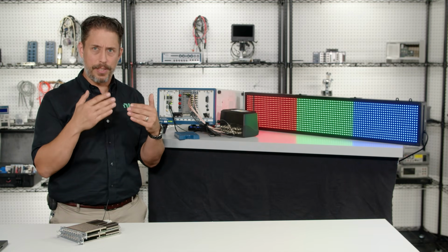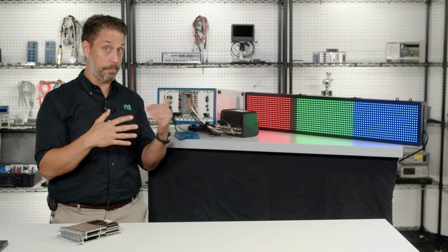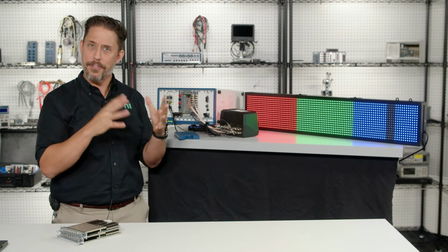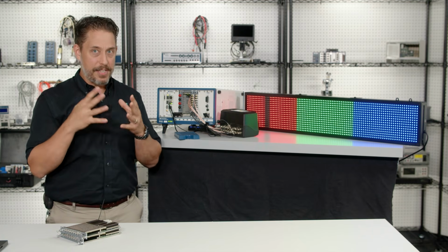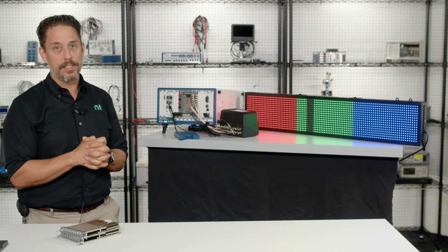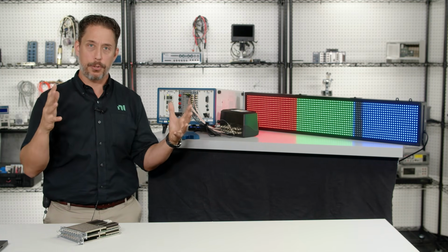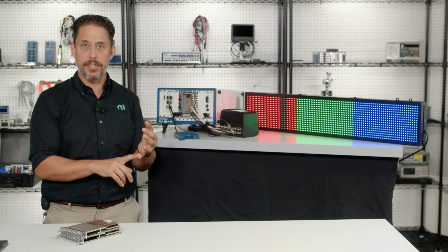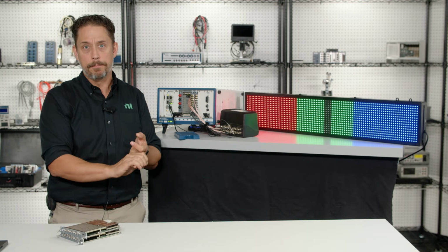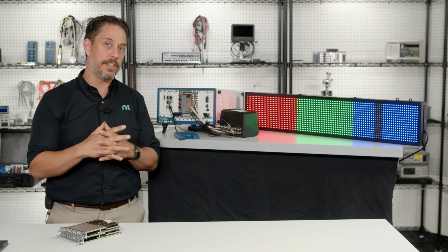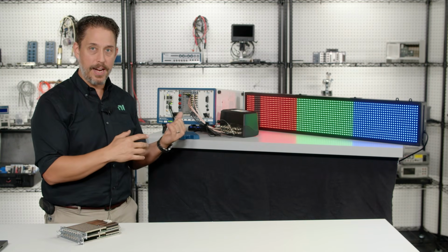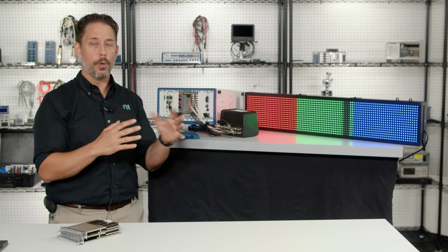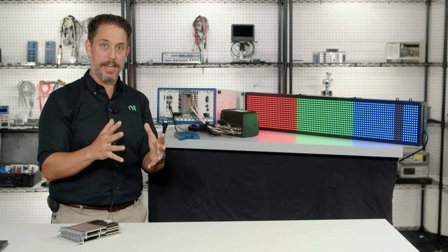But the minute that you start to really go beyond 2 and 4, or going to 16 or Lord only knows 136 channels, the data throughput could take a very, very long time, up to 4 seconds just to transfer the traces to the computer to continue to do whatever experimentation, characterization, validation, even production test. And so one of those differentiating features of modular instruments within PXI is the access to massive amounts of data, be it for streaming or just getting one record of many, many channels.